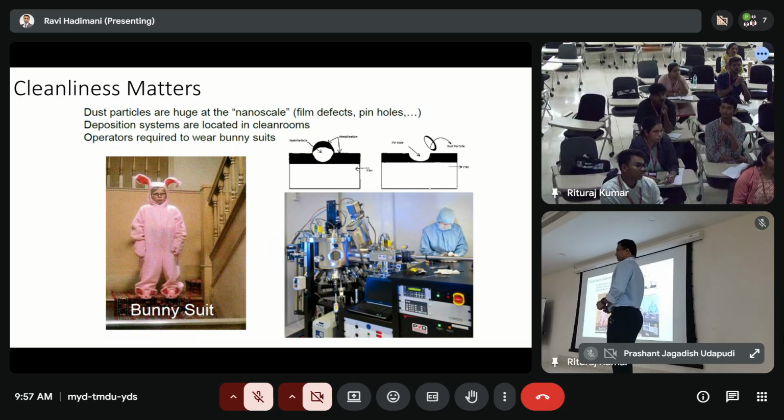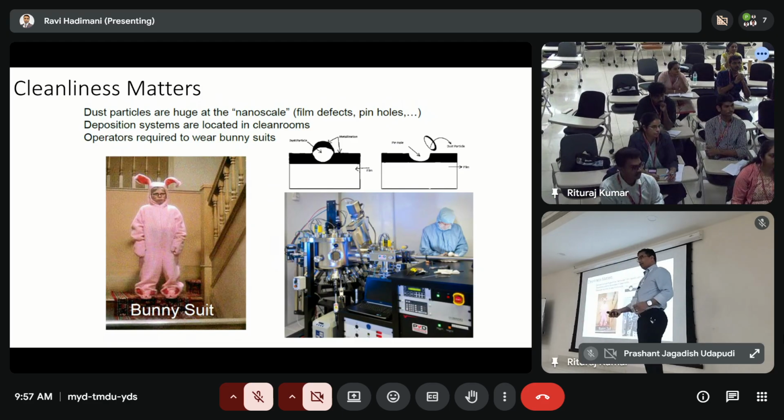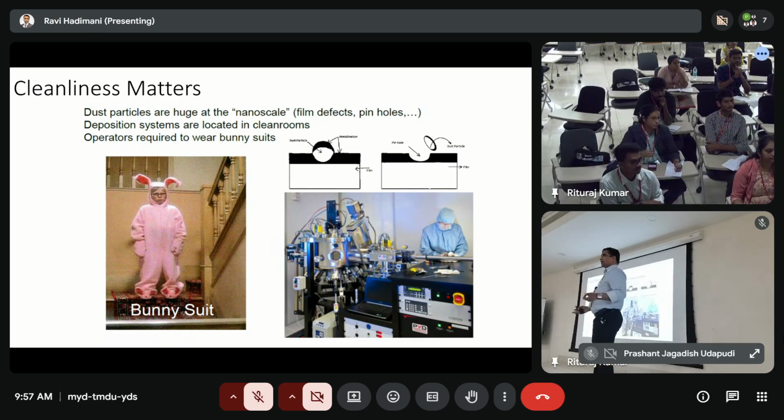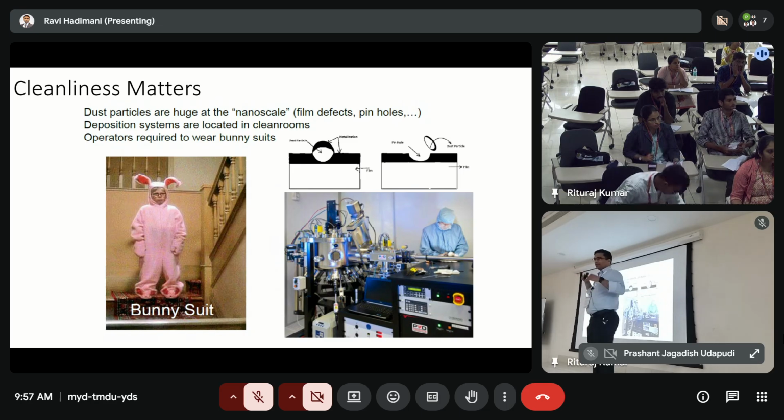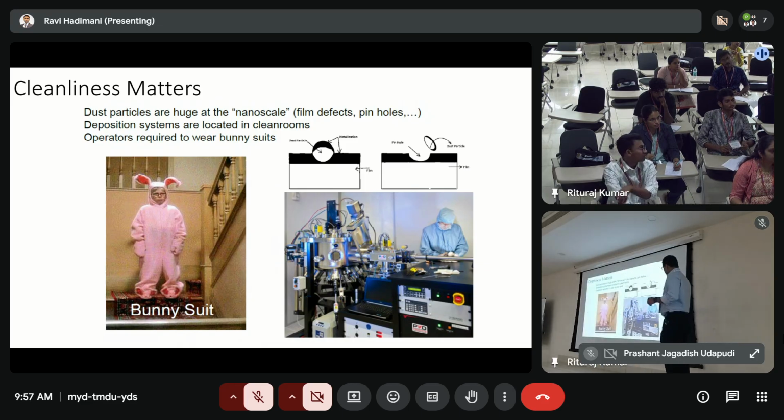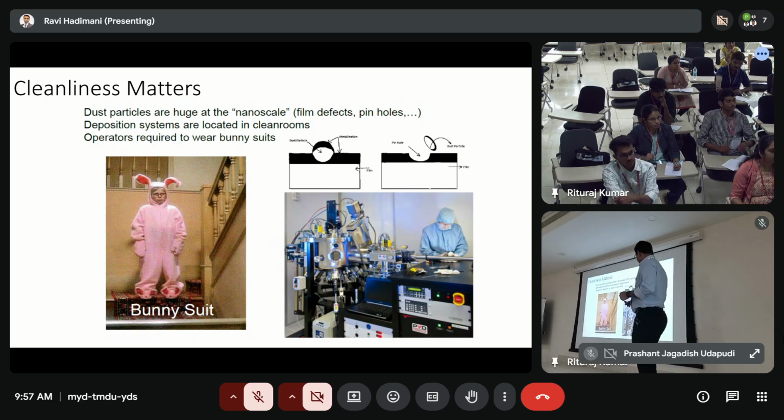So yeah, it's a similar setup, except that the pressure is kept at negative level, and there are different classifications of clean room: 1,000 level, 10,000 level. 1,000 I think is the cleanest, and as you go to 10,000, it becomes a little dirtier. I wouldn't call it clean here, but some particulate matter is acceptable, up to 10,000 per meter cube. Okay, so that's the clean room setup.